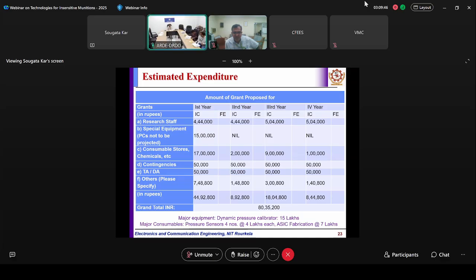First thing, we want more resolution. 12 bit is less resolution for us. Yes, sir. That would be fine if the 12-bit resolution is less. Even the memory is less. I think when we are sampling at a very high rate, you may require more memory depth. And then we want the system with both input as a voltage as well as this IEPE.